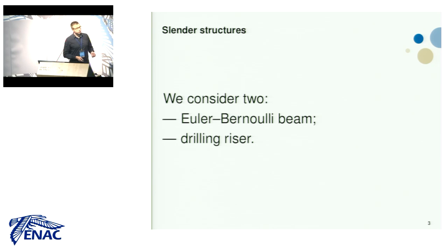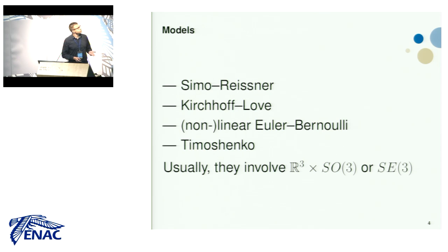In this work we considered two of them. This is a very simple Euler-Bernoulli beam which is clamped on the sides, and a drilling riser which is used in offshore oil rigs. This is the beginning of our work in this topic, and we use quite simple models which are adapted from several other more general frameworks like the Simo-Reissner model, Kirchhoff-Love model, nonlinear and linear Euler-Bernoulli descriptions, and the Timoshenko beam, and others.